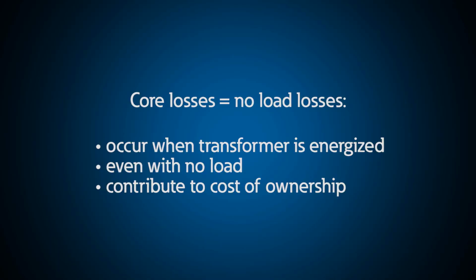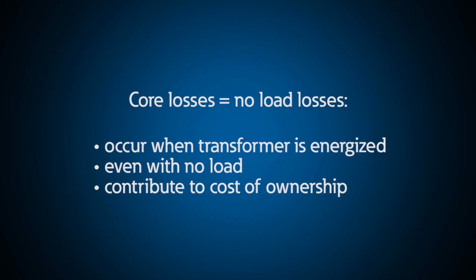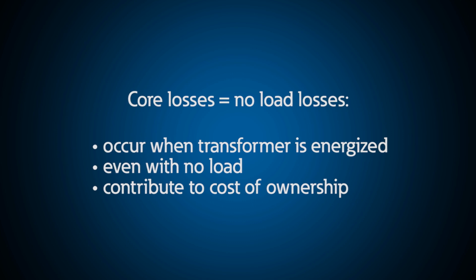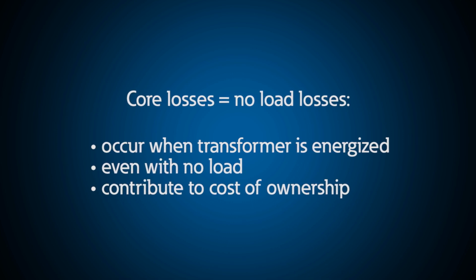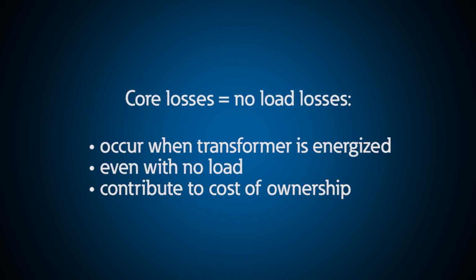Different core types, sizes, materials, and grades can all affect the operating losses of the transformer in the form of core loss. Core losses, also called no-load losses, occur continuously while the transformer is energized and can contribute significantly to the total cost of ownership.